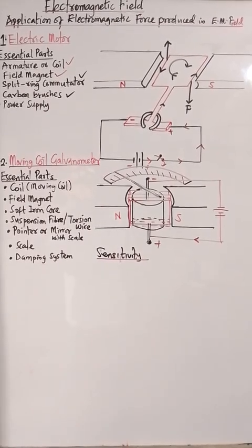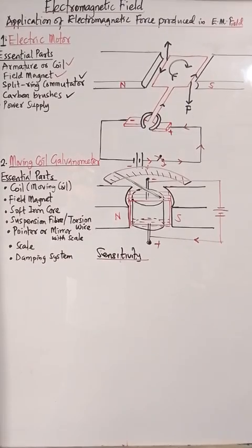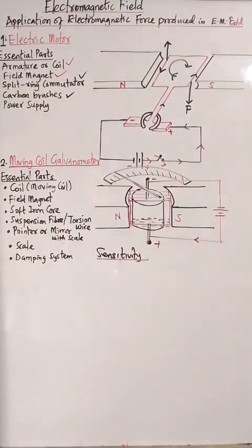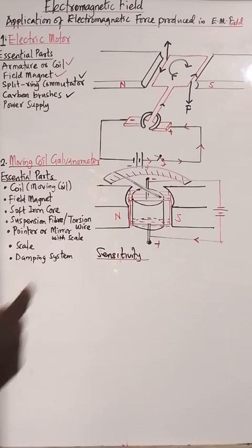To increase the sensitivity of a galvanometer, first, the magnetic field must be extremely strong. Secondly, the number of turns of the rectangular coil must be increased, as we have many turns there. Third, the area of the coil must be increased. Lastly, the spring should be made of thinner wire to enable it to twist more easily. Such weak springs give only a small control couple, and because of that, the galvanometer has many advantages.